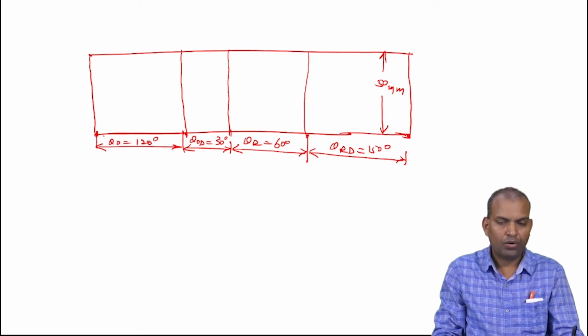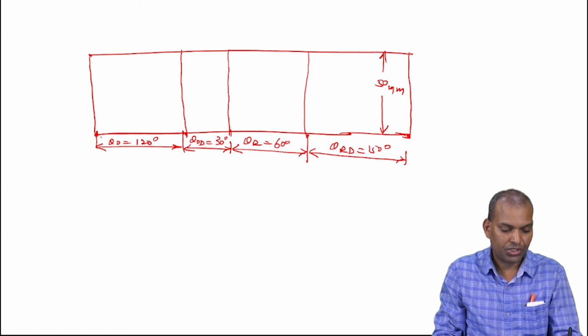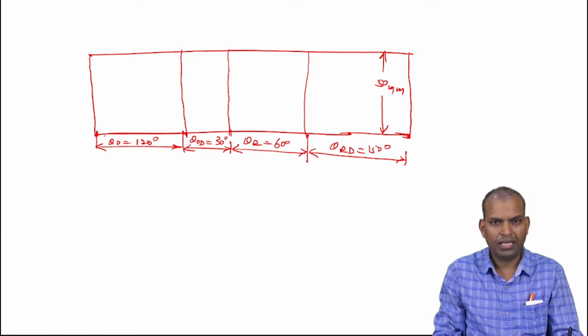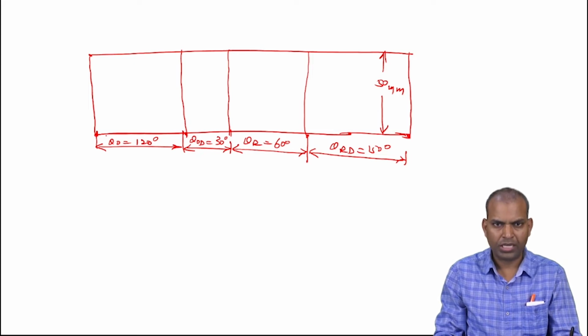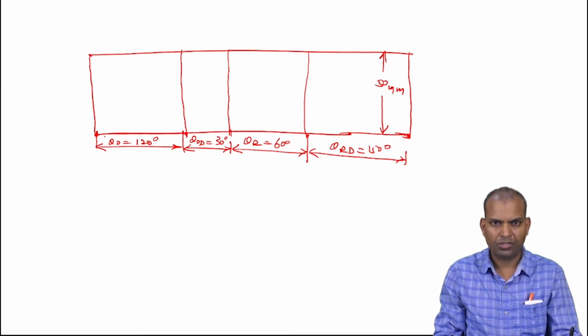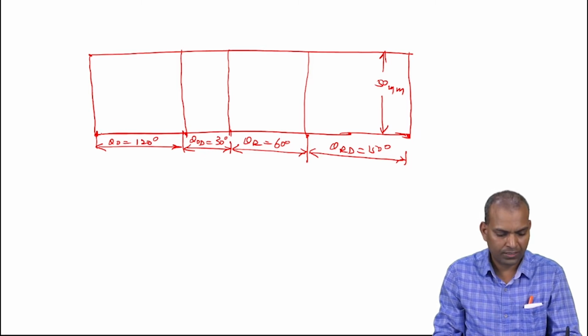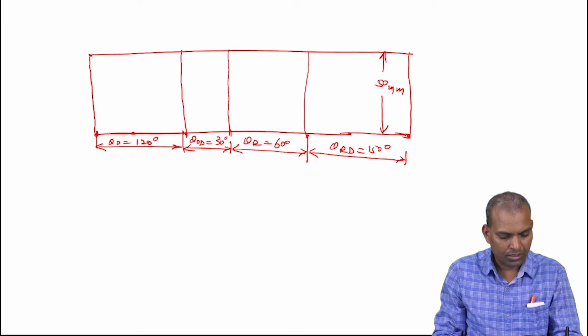okay. Now after that, what to do? Divide this outstroke angle length into equal divisions, an even number. So 4 parts, 6 divisions, 8, 12. I am considering 6 parts, it's optimum. There were 6 parts you consider, so each indicates 1 centimeter.